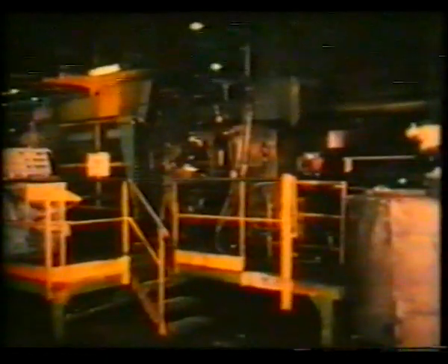Our die casting machines are mainly applied in the automobile industry. This cold chamber machine with a locking force of 20,000 kilonewtons turns out 20 engine blocks per hour with a shot weight of 30 kilograms. Thanks to advanced die casting technology, it is possible to manufacture even such complicated parts efficiently and with great precision.